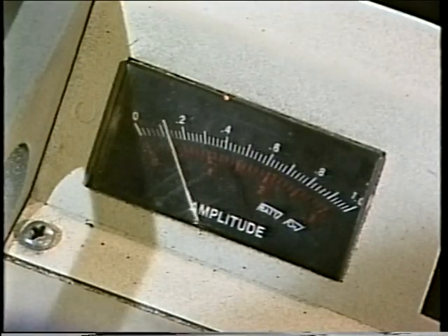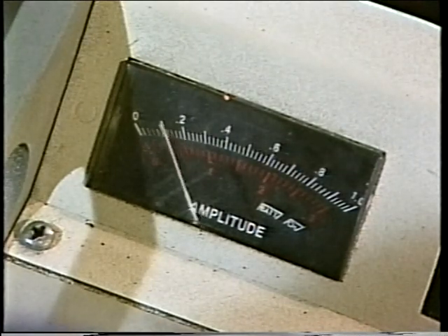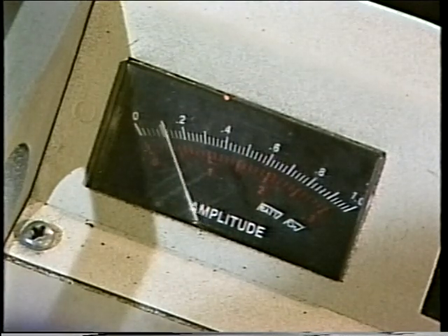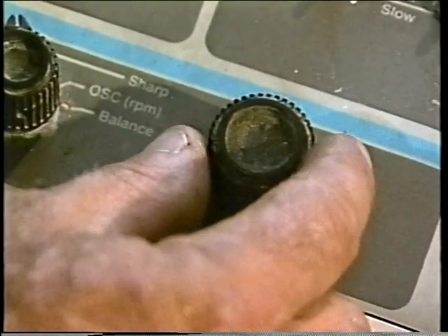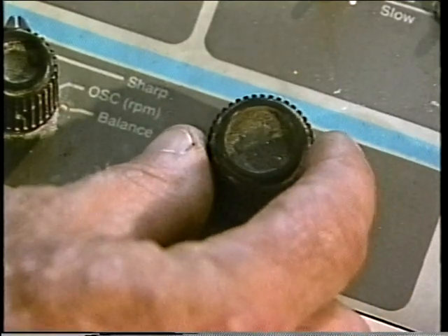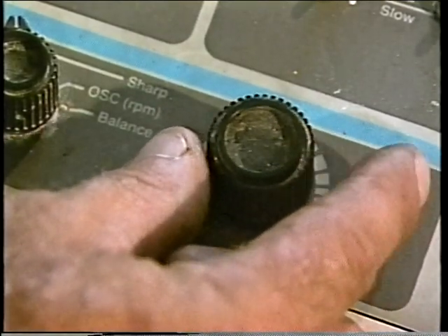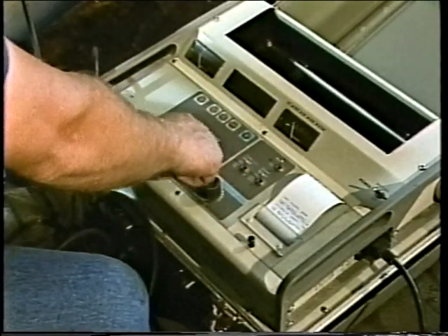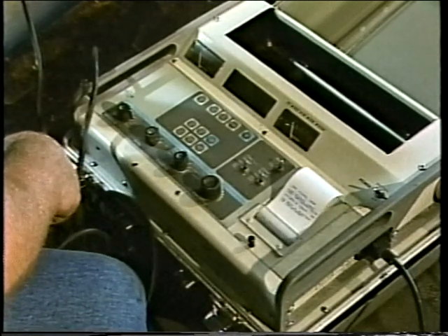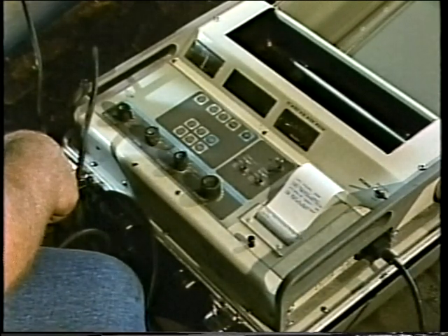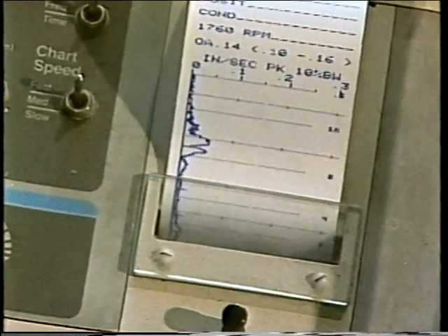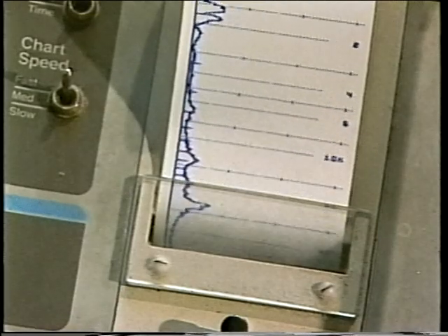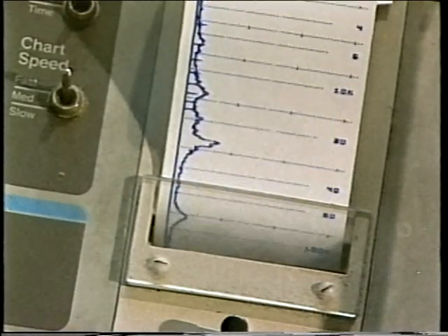The analyzer then displays the level of vibration at 1,790 cycles per minute, plus or minus a certain percentage, in this case, 5%. Once the amplitude of the vibration is determined, the analyzer can be readjusted as necessary to concentrate on another specific frequency. This process continues until all desired frequencies have been checked and each corresponding vibration level has been noted. To get a printed chart of the reading, the printer function is selected on the analyzer. The analyzer then prints the chart, again with a plus or minus 5% bandwidth.